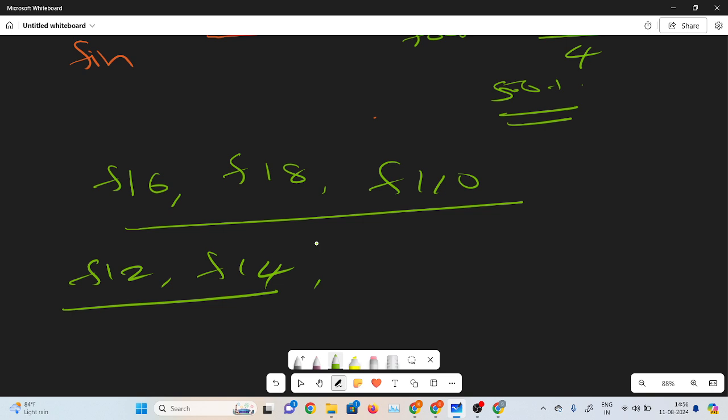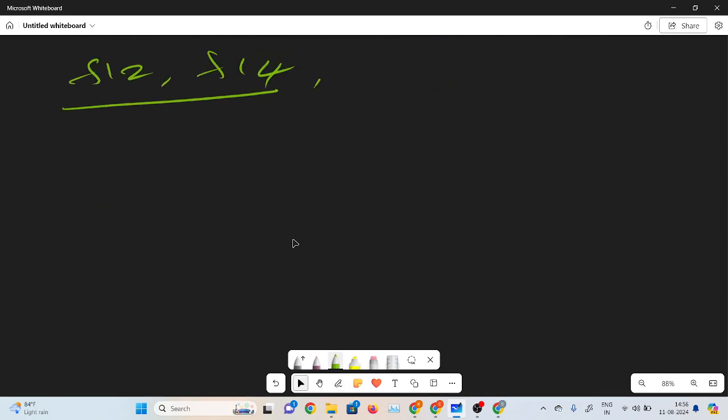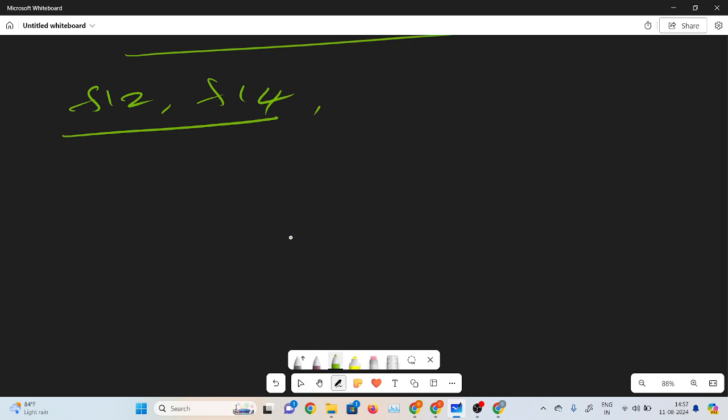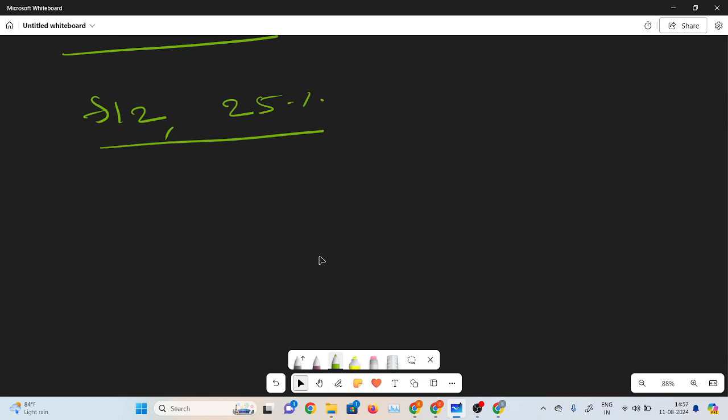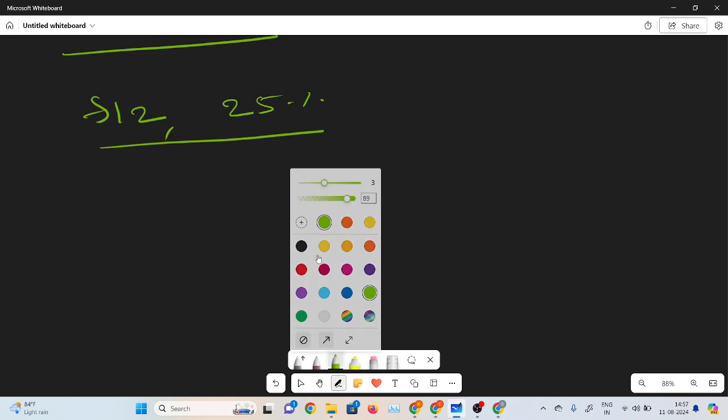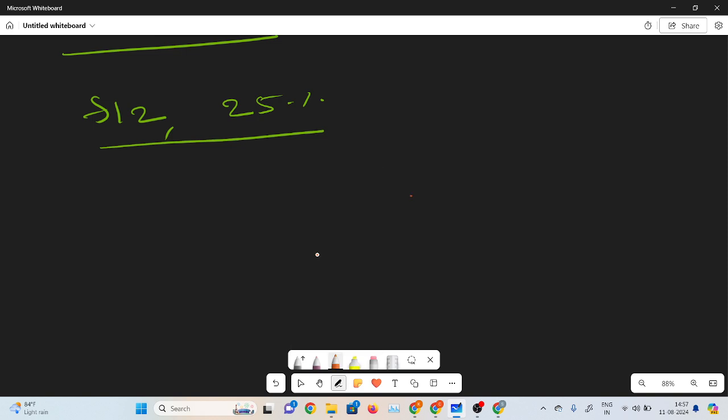Of course, the duty cycle can also be changed with the help of an external gate. Suppose I am taking the f by 2 circuit again, but in this case you need to design the f by 2 circuit with 25% or 75% duty cycle. I can make that here easily. I just need to use an external gate to change its duty cycle.